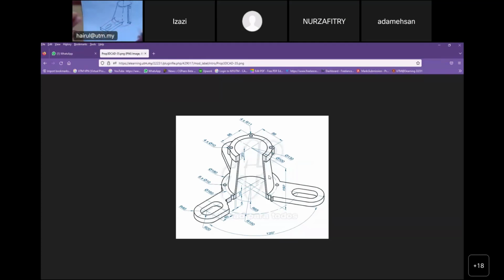And we just learned about circular pattern, right? Circular pattern. So you can select these edges, circular motion, and they become okay. This one is already filleted. After that you fillet both sides and do the slot. Then you circular pattern all these features, so then you have this arm 3. Circular pattern with the number of 3 or 360. What is the reference? These edges work as long as you have a full circle here. That's how we do it.